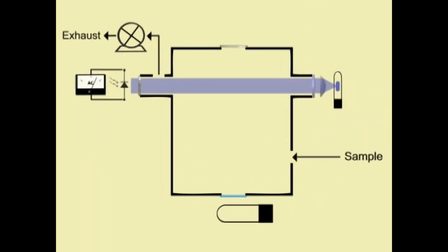There are a couple of ways to calibrate this process to zero gas condition. The first is to flow nitrogen into the measurement chamber and record the resulting signal voltage. A second way would be to turn the UV lamp off: no ultraviolet light, no fluorescence, no signal voltage.